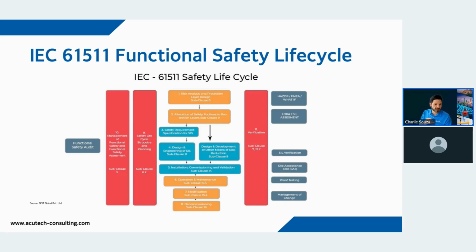And if we get audited on the PSM, you're going to have your FSM, your functional safety management documentation, ready to be provided to that auditor. If the auditor decides to go a step further and start asking you safety instrumented system related questions, right? And you may say, well, we've been audited before, internally, externally, and even by OSHA. Nobody has asked us any questions about 61511. Nobody has asked us any questions about functional safety management, or we have never had to show any documentation.